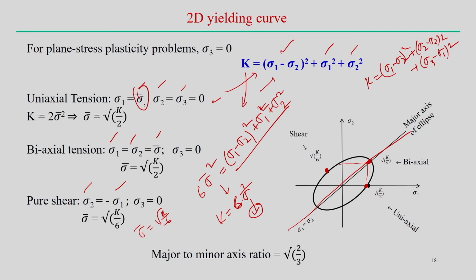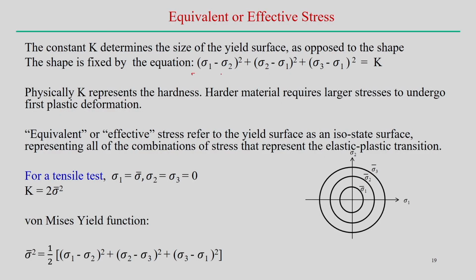So, that means depending upon the experimental condition, this constant term can be defined. Whether we are following the pure shear condition and measuring only the shear yield strength, or the normal yield strength if we consider uniaxial tensile testing, this constant term can vary. Therefore, this constant term k, because we represent the functional form equal to k, can be defined depending upon the experimental condition or the value of the yield strength measured in different situations.